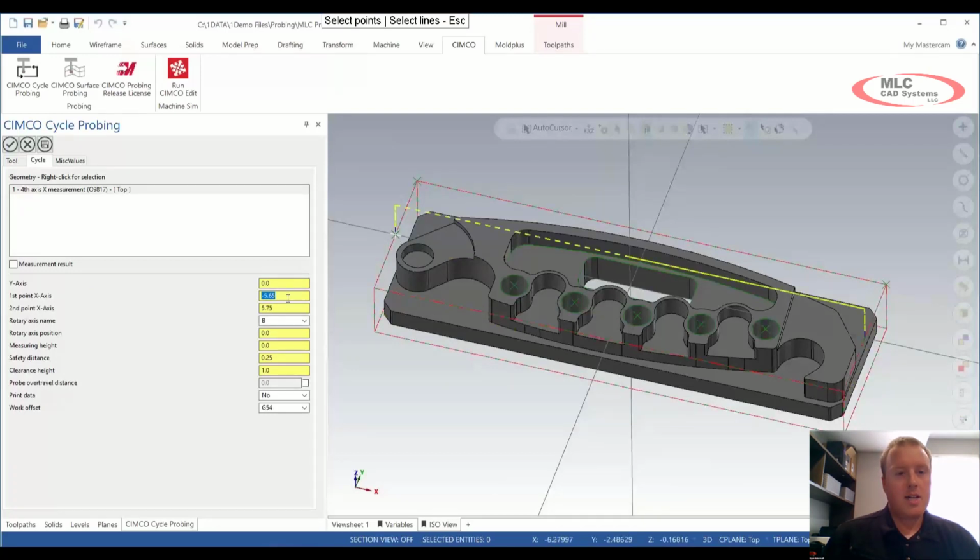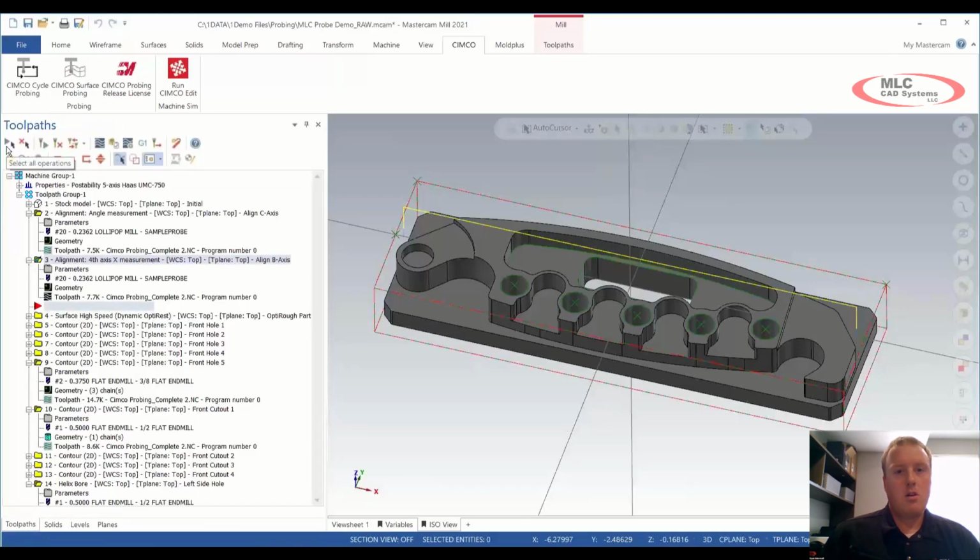And then, of course, as I did before, we can simply bump those in, a couple hundred thou. Again, still getting an even spread across my part. But then, of course, with that, we're going to go ahead and update my B-axis in a G54. And again, that's going to allow me to go ahead and flatten that part out.